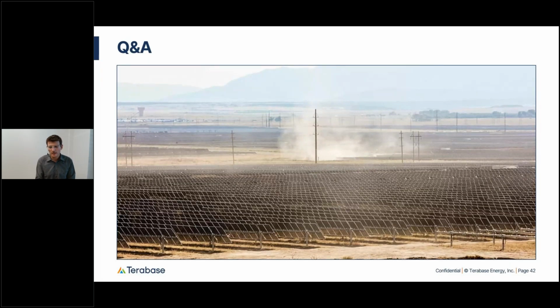As we showed in the presentation, we can compare the measurements against our models and see if we can tweak some of the model parameters to get a better fit. Then we use that model to run on the entire historic data set, and as a means to predict the soiling for the next year. That should give you better results. In that way, your measurement is a way to include more localized effects into your prediction. And if you have such a case, please reach out. This might be a great validation project, and for us a chance to learn how to improve.